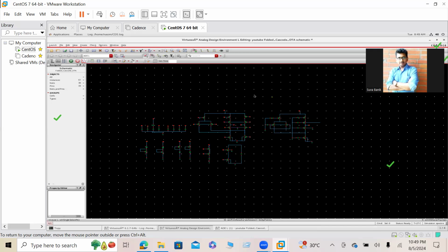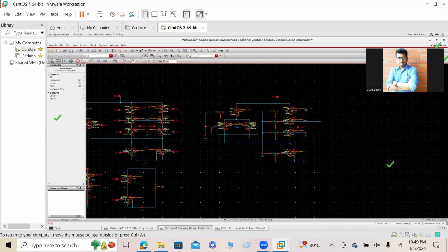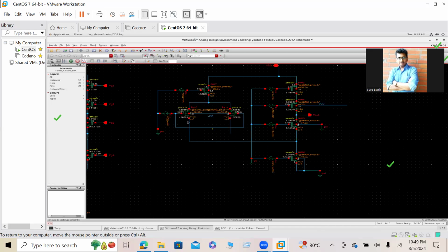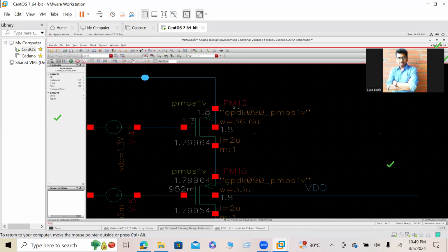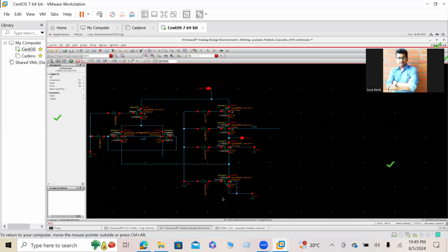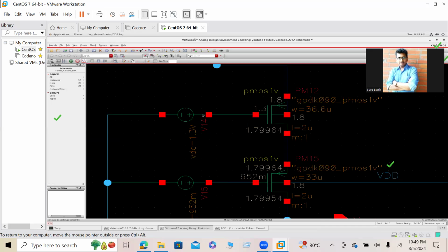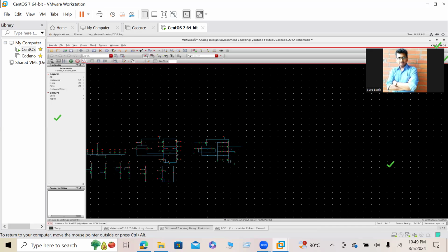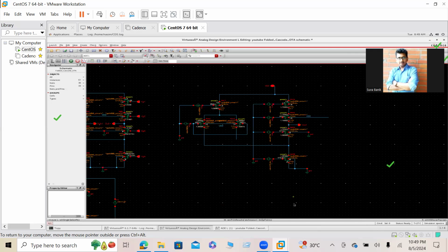Now, whenever we calculate and find everything from our calculation, I just design the half circuit. This is the exact WL value, whatever I find here from my calculation, and this is the exact value of the gate voltage from here. Okay, so from here, I find that some transistors are not in saturation. As I explained, we are not calculating the lambda value, and we are using the same mu n and mu p value for everything for simplicity. So we need to just tweak the circuit to match the formula.